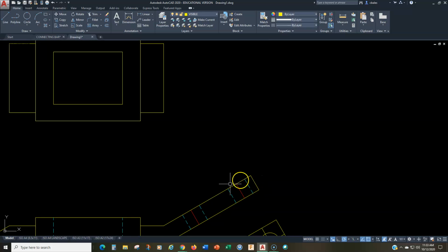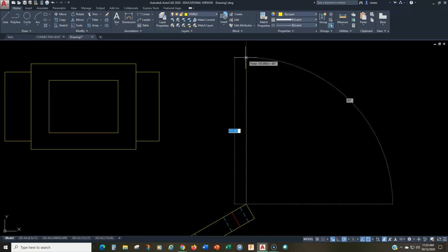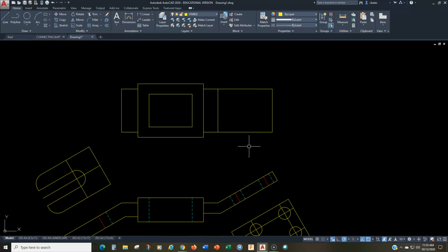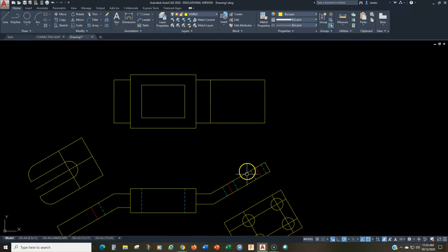Let's do the top, okay? So we're going to focus on the top of this surface, which is going to be the top in the top view. And I'm going to project this line directly up, and I'll just shoot past like that. And then I can extend this line like that, and we can trim that off. All right, so there you go. That's the foreshortened view of this feature. Okay, now you can see in the back that actually, if we're looking down, I'll draw a line.